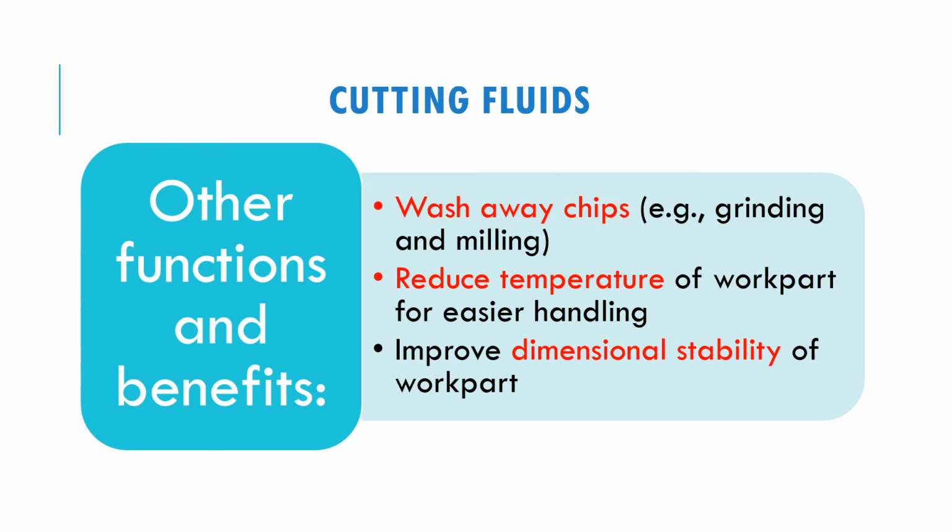When it goes out from the machining area, it can fly to the worker who works on the turning or milling process, so it is very hazardous to the operator. So it can reduce that temperature. It can also reduce the temperature of the workpiece, so that we can easily take it out after the machining process. It can also improve dimensional stability of the work part.